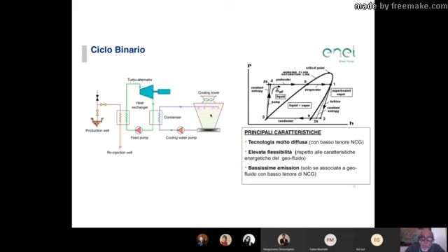Now, since the cooling towers are much less efficient if they're run on air, that means that you will need a much larger space on the surface where you need to put your cooling tower. So your cooling tower occupies about 10 times the space of a cooling tower run with evaporating water, an evaporating cooling tower.